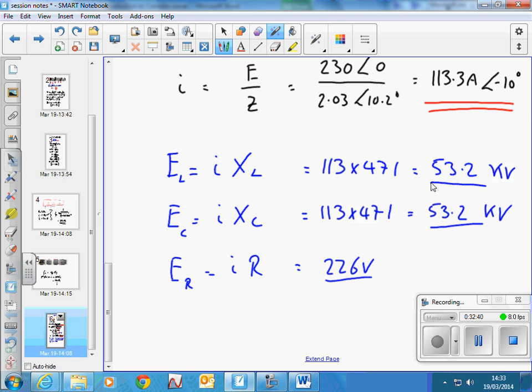And our supply voltage, remember, is 230 volts, so 230 volts across there is nearly all across there, but we get these huge voltages. Think back to when we were talking about sloshing circuits and sloshing water in a bath. Once it's going, you don't need to put much energy in to keep the system moving. And in fact, the energy builds up until you get these massive voltages across the components, far greater than the actual supply voltage we're putting in. So we're going to damage circuits if we allow this to go unchecked. Okay, so we need to take precautions.